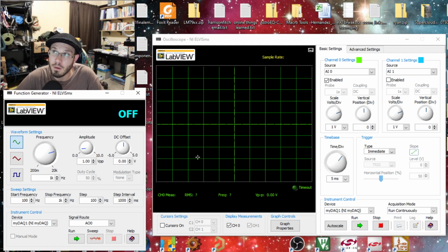Okay, so that means our peak voltage is 0.5 volts. So it should go up half a volt and then come down to a minus half volt. Now our DC offset, this is how far away the center of that sine wave is from our 0 on the y-axis. And we're going to leave that at 0 volts. We want it centered at ground. So this is going to go up to positive 0.5 and down to minus 0.5. And at least that's what I think by these settings right now.